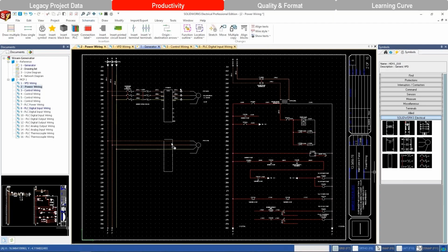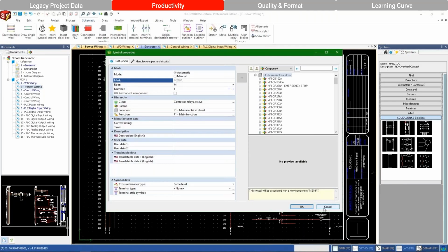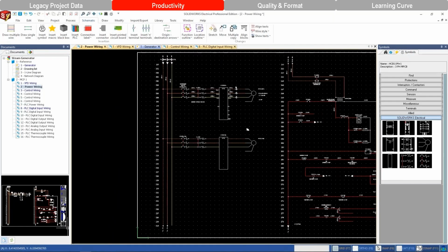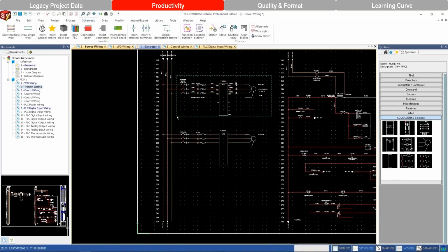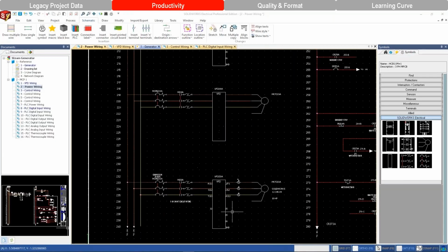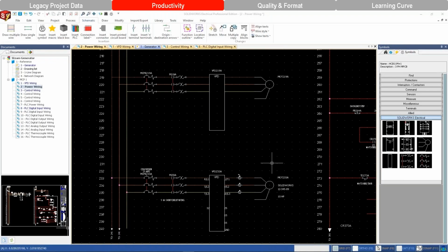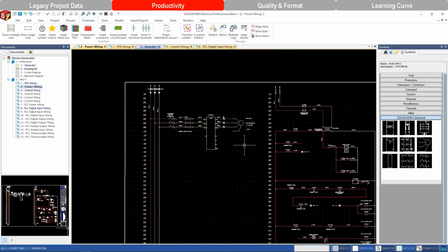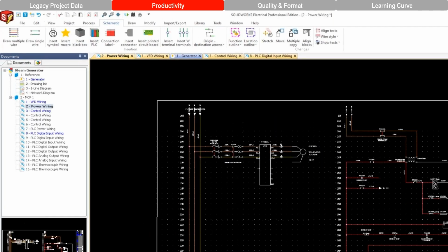In this example, I am quickly laying out a circuit without defining any additional metadata content. I'm showing you this just to demonstrate the flexibility. I can work with manufacturer's part information, or I can work without it. And so, just quickly, you watch me do it. I created an intelligent circuit. Now, furthermore, just with a simple Control C and Control V, anything I reuse is fully intelligent. Notice that I moved that to 233 and all objects retagged to remain unique for its new location. Nothing was duplicated, even as simple as a Control C and Control V.